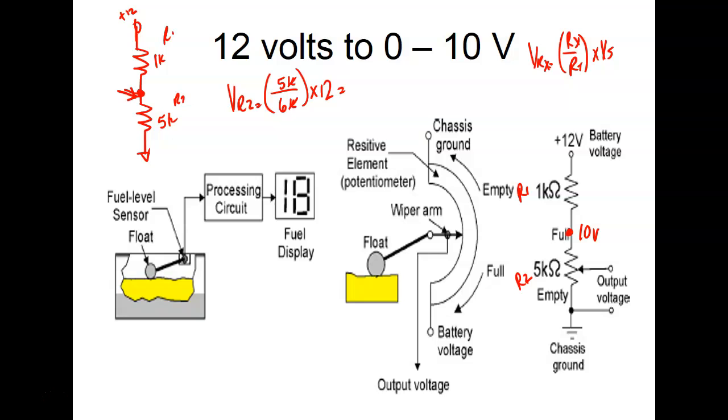Now say I raise the voltage up or lower the voltage down. That resistor would always drop this ratio in a series circuit. I've had this happen before too. I say, okay, calculate your current, and then what happens if I change to a 6K? And one of the answers in DC would say the current would be the same because it's a series circuit, but it's not the same circuit. You'd be surprised how many people answer that.